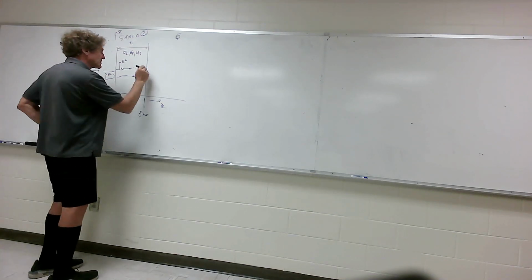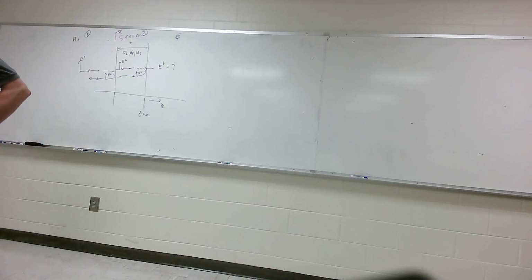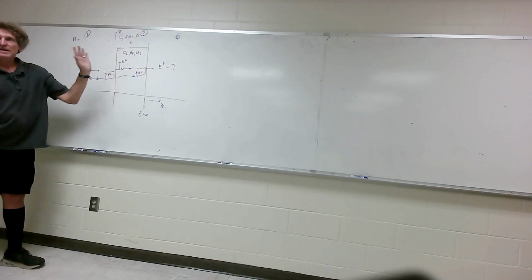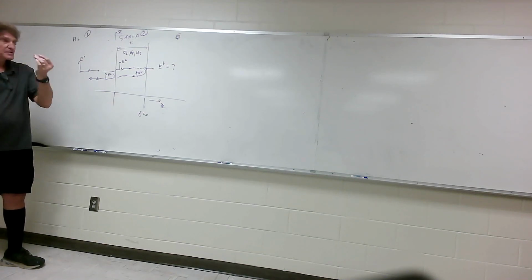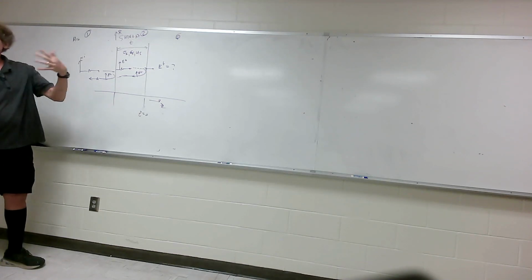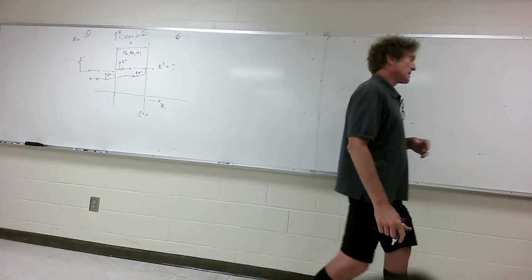What we're after is this. We want to figure out the electric field transmitted. That's our goal. And then we'll find a way of attaching a figure of merit to that, which we call the shielding effectiveness. So what is a shield? You're trying to shield something from electromagnetic radiation. So this is typically made of something like copper. It's very thin, of the order of maybe tens of microns, maybe 100 microns thin. It's preventing electromagnetic fields either from getting out of a region or from entering a region.